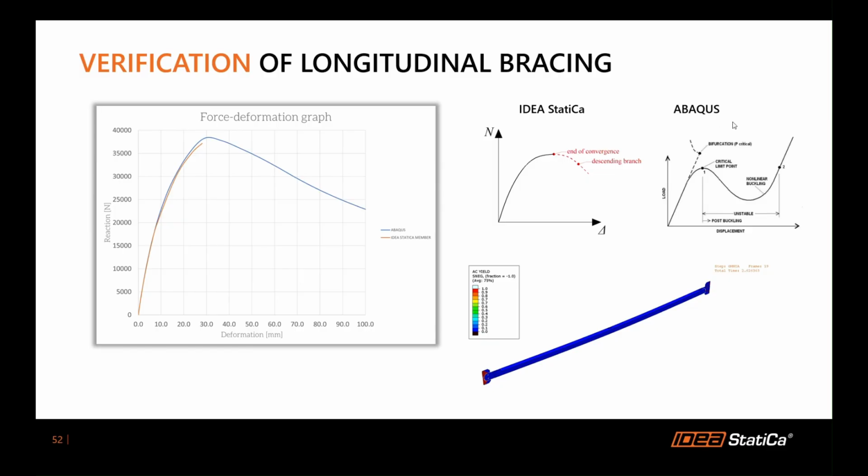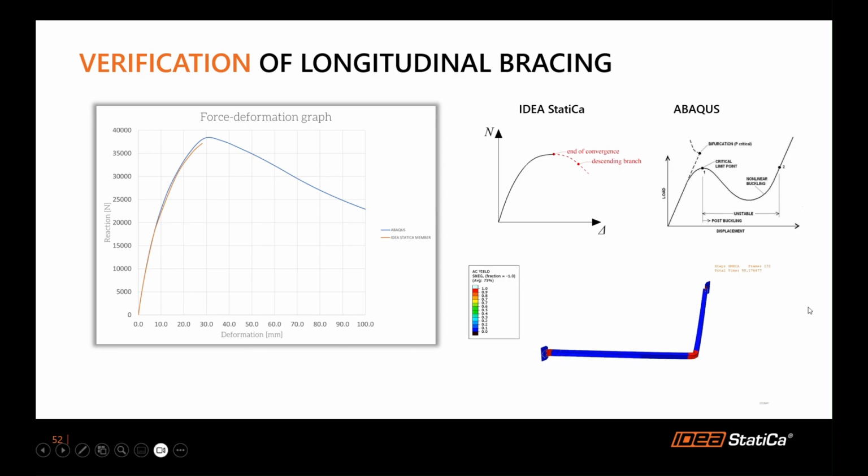In Abaqus it is possible to go on, because what you do there is you apply the deformation and you calculate the force. In IDEA StatiCa you apply the force and you calculate the deformation. Now, the last thing I want to show you is this in Abaqus. So that means after buckling, after instability, you can still perform the analysis and you get nice videos.